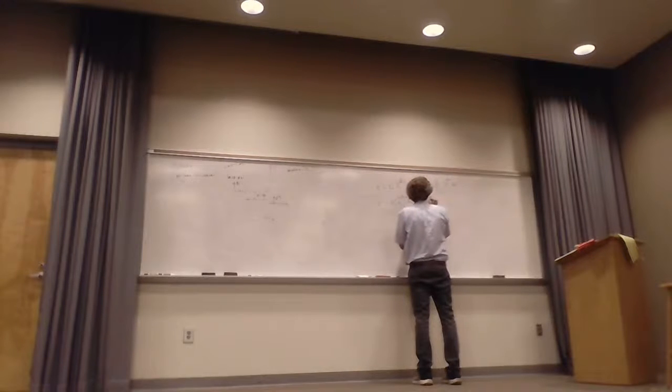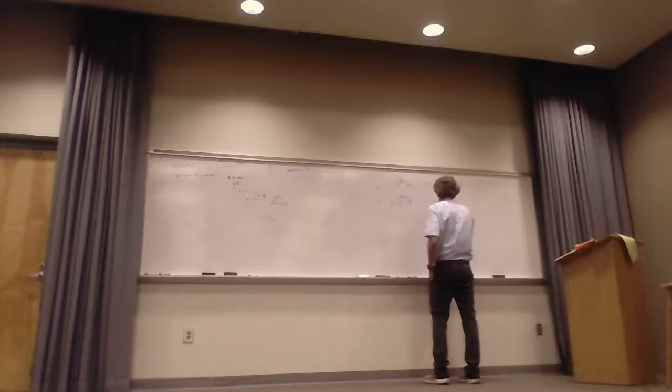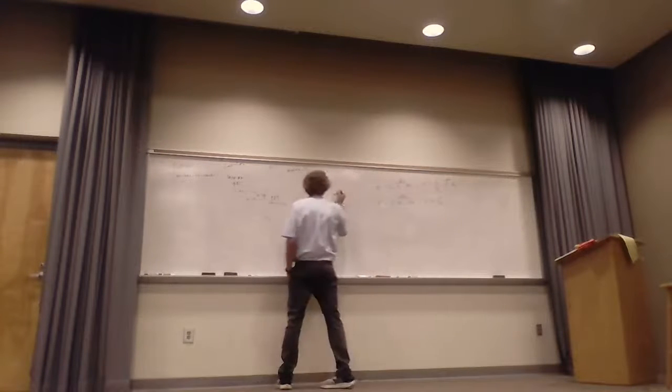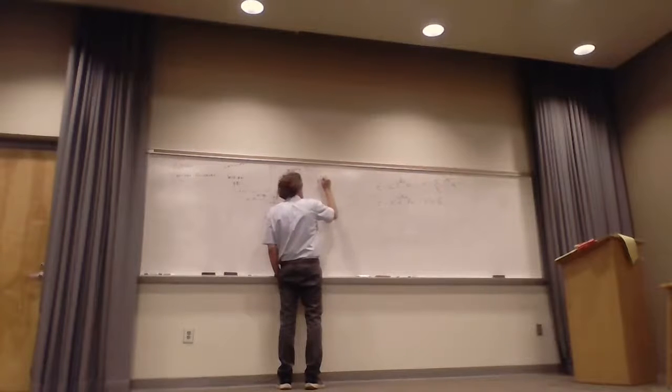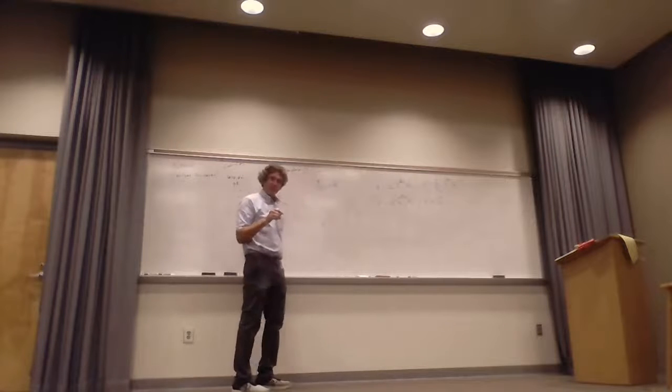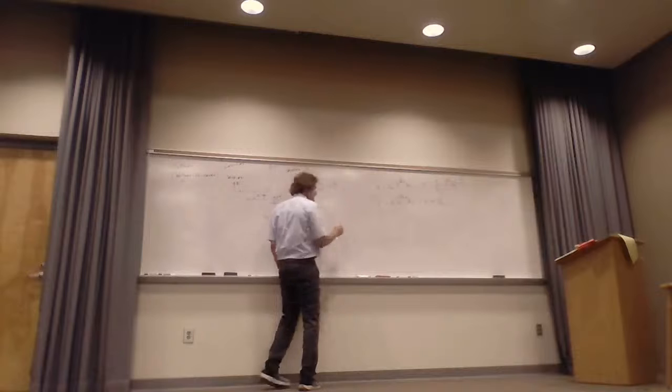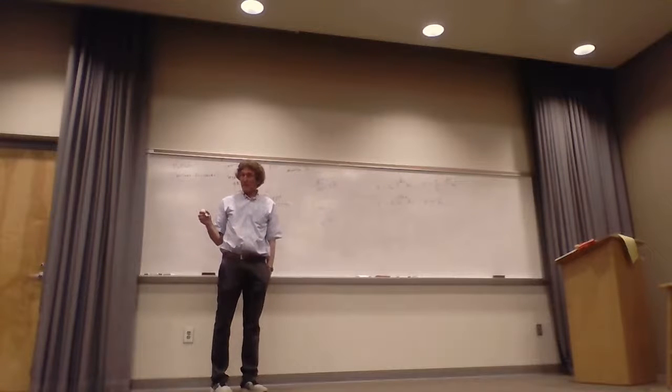Then H reflected is equal to E naught reflected right there. I think I did this last time. Do you remember when I said the ratio of E naught plus to H naught plus was equal to the intrinsic impedance? I think I said that the ratio of E naught minus over H naught minus was minus that. Do you remember that? Kind of, sort of?